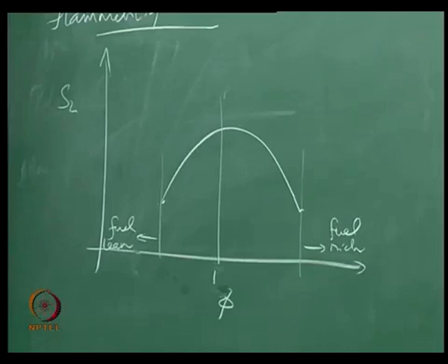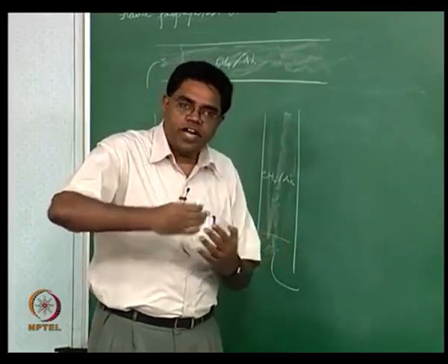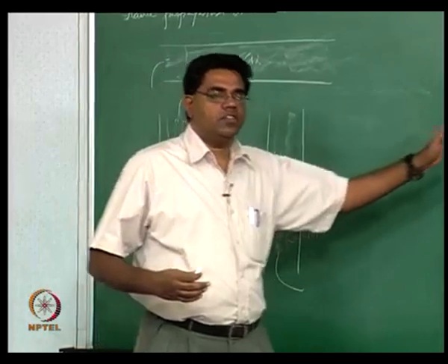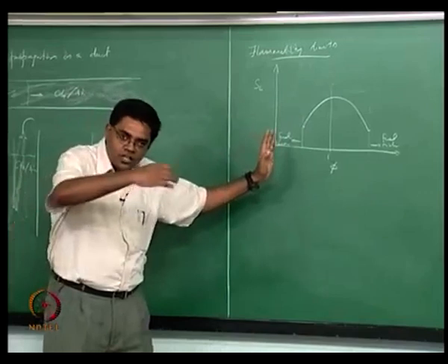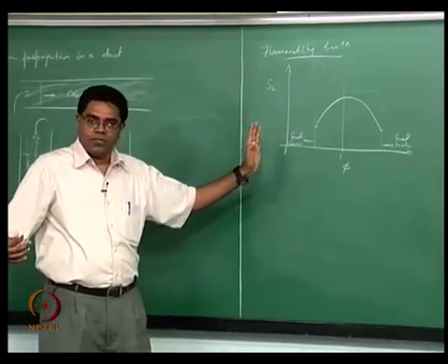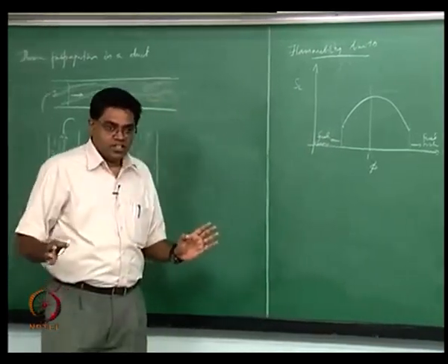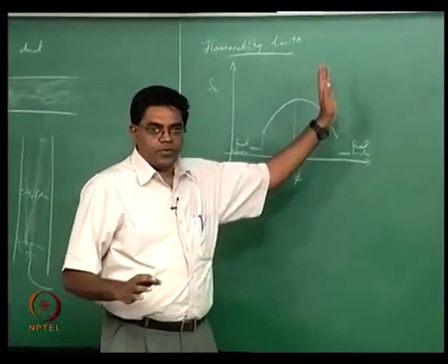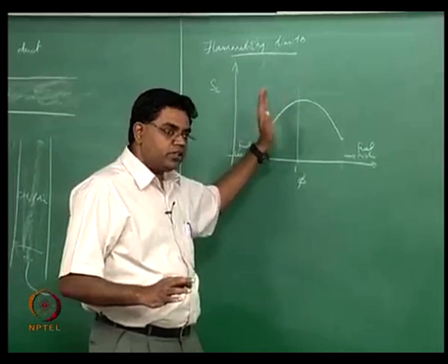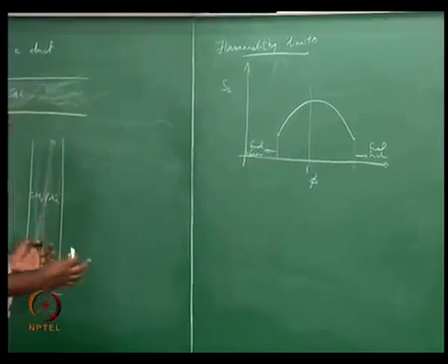And at these limits you have a significant role for chemical kinetics coming in. What is the effect of chemical, what are the set of reactions that are happening, and you are now starving the system of one reactant to start with and then the corresponding set of radicals that are there, okay. So the chemistry can significantly play a role over here, and for this reason the flammability limits are somewhat empirical. I mean the knowledge on flammability limits is quite empirical even to this day. You have to significantly work on the theory to be able to explain this correctly.